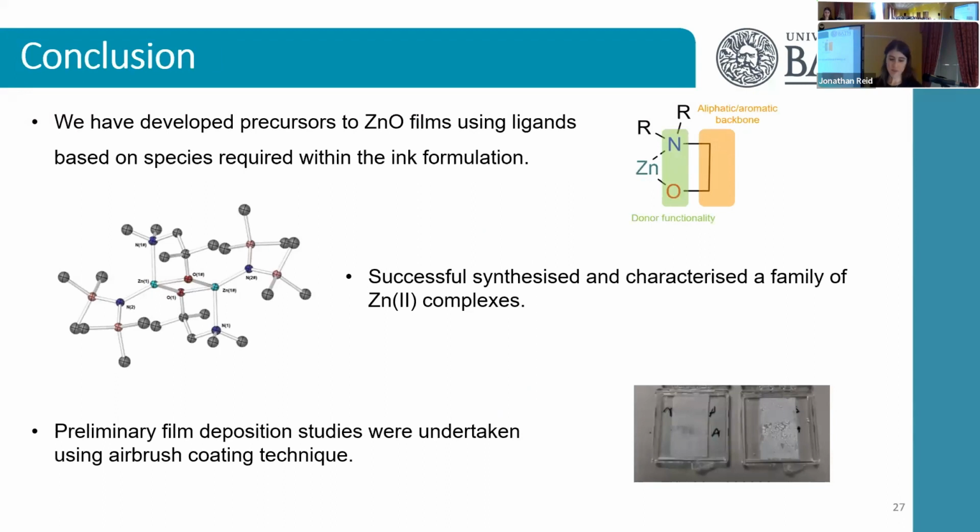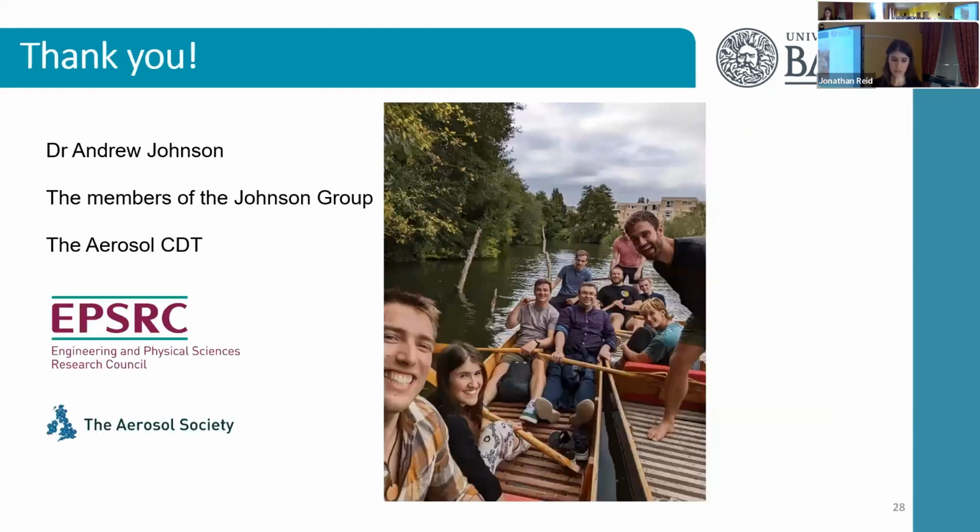So to conclude, we've developed precursors to zinc oxide films using ligands based on species required in the ink formulation. We successfully synthesized and characterized a family of zinc-2 complexes, and we deposited one of our synthesized complexes using this airbrush coating technique.